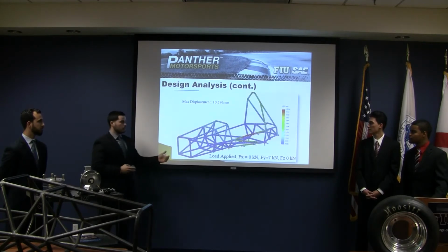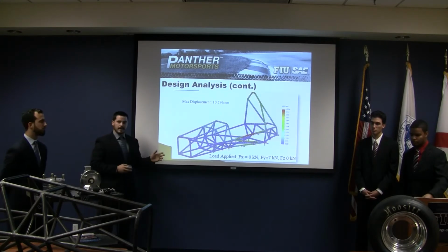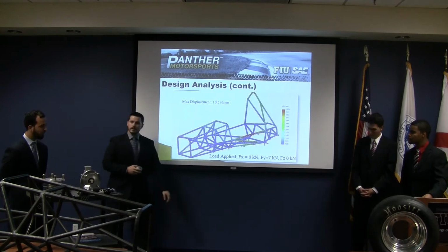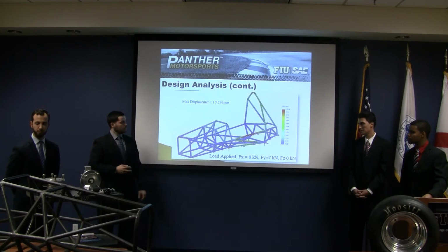And here we are simulating what a side impact would be, resulting in a maximum displacement of about 10.5 millimeters. And we see that the maximum displacement would be in the upper side impact member. The reason for that is the upper side impact member is the most perpendicular to the applied load.